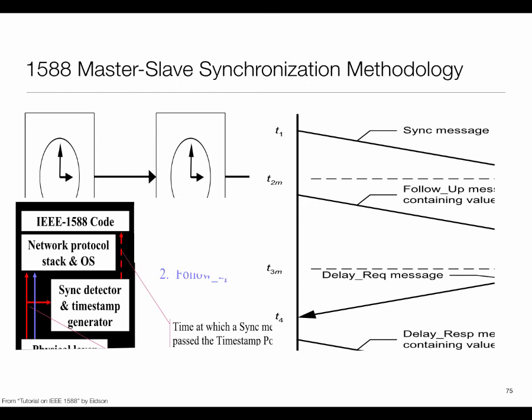It's a standard, and you can now buy network cards and Ethernet chips which support 1588. In effect, they do the timestamping which is required by 1588. Original Ethernet boards did not have any timestamping capability, so any timestamping was done by the operating system, and that's why things were less accurate. That is why NTP is as inaccurate as it is, because within the Ethernet packet there is buffering and all that. 1588-compliant Ethernet takes care of it.